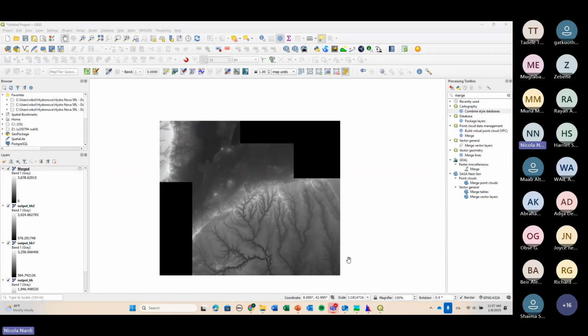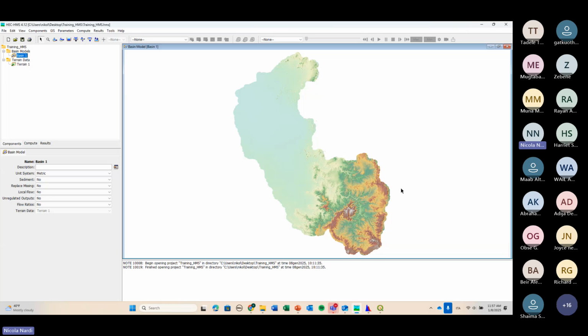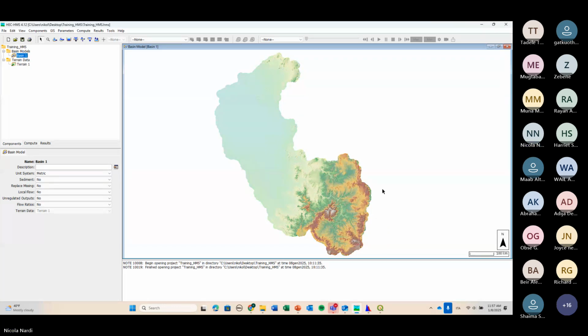This is exactly the same thing that happens here, okay? For the study at Atbara, we knew in advance, more or less, what the basin looked like. That's the reason why you see that this DEM is really accurate, really clipped, and you will see later on the edges of the Atbara subbasin.